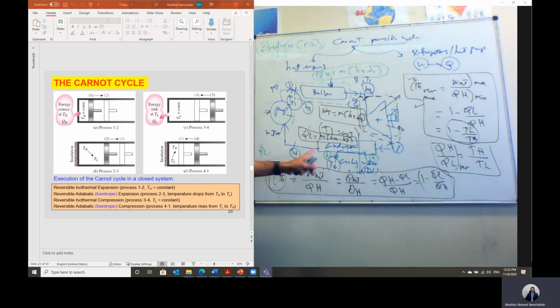This is a heat exchanger. So the heat absorbed by the cooling water equals the heat rejected by the hot stream from state 3 to state 4. So Q dot low can equal M dot cooling water multiplied by delta H, which is HA minus HB. This is for the cooling water. If pressure and temperature are given, then we can go to the steam table, calculate HA and HB, and then we can calculate Q dot low.